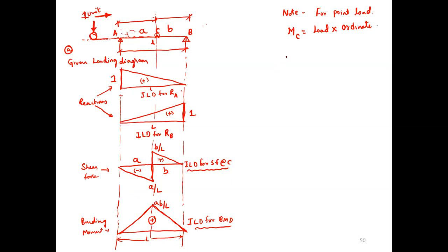Okay. Similarly, for UDL, for uniformly distributed load, moment at C equals load into area. Don't confuse. Load into area, for which kind of loads? For UDL kind of loads. Load into ordinate, that is height, for which kind of loads? For point load. These are the two things you have to remember while you are solving the problem.